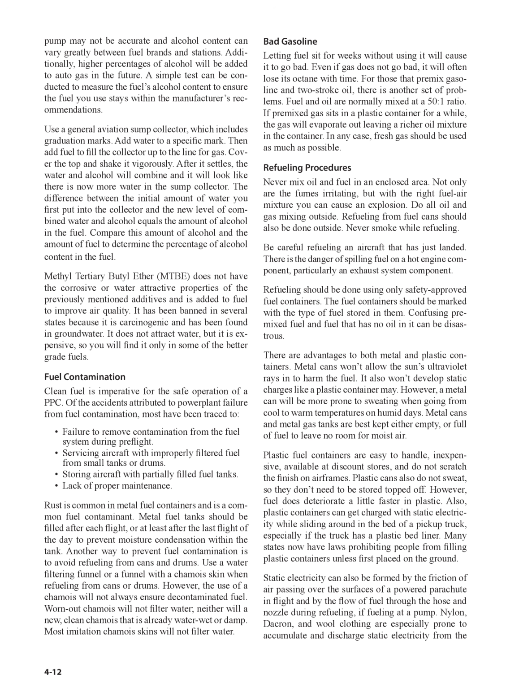Metal cans won't allow the sun's ultraviolet rays in to harm the fuel. It also won't develop static charges like a plastic container may. However, a metal can will be more prone to sweating when going from cool to warm temperatures on humid days. Metal cans and metal gas tanks are best kept either empty, or full of fuel to leave no room for